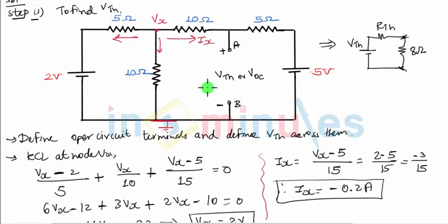that you come across. I repeat, to find any potential difference between 2 points, we start from its negative polarity, travel to its positive polarity, and go on collecting all the voltages in the path. You can go through any path you want, the voltage difference will not change. We do not travel through a path which contains a current source, because if you remember, we had seen this before, you can't define the voltage across current source in KVL equation. Whenever there are multiple paths available, we always choose shorter paths so that we have to add lesser number of voltages.